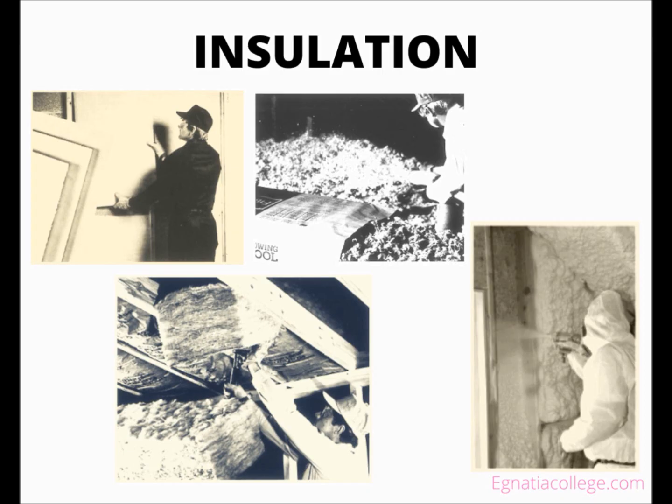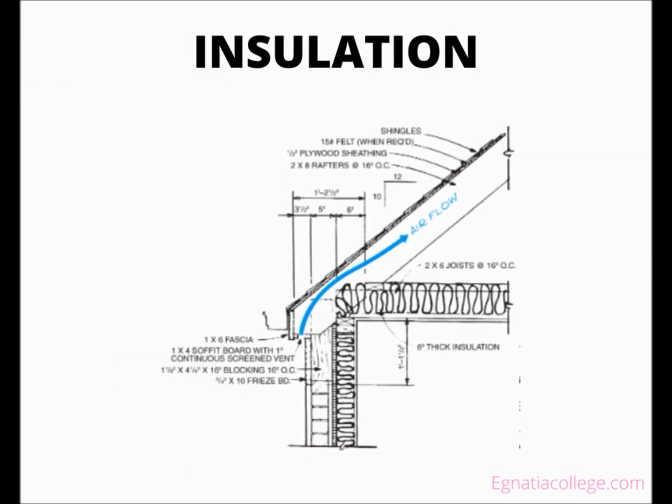Blanket insulation is in the form of flexible rolls or batts usually made of fiberglass wool. Loose pouring insulation can be any of a variety of materials that can be poured into place and has good insulating properties. A common pouring insulation is loose fiberglass. The insulation is shown in the building sections. If the insulation is to be installed between studs, joists, or rafters, it will be sized accordingly.